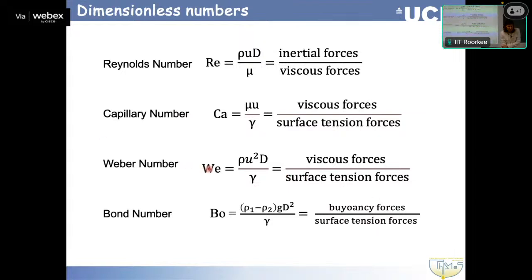And then there is this Weber number that you can obtain from combining different types of numbers as well. But this is a mistake here. This should be inertia over surface tension force. I'll correct that. So you can say that these numbers are equivalent if people have worked with dispersed flows. When our flow rates are low, the capillary number is more important because viscous effects are more important. When the flow rates increase, then the inertial forces become more important. So the Weber number takes over.